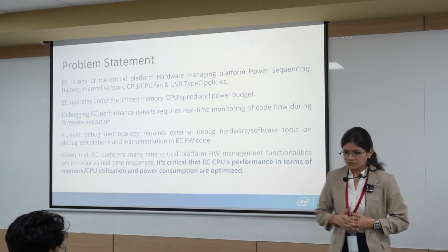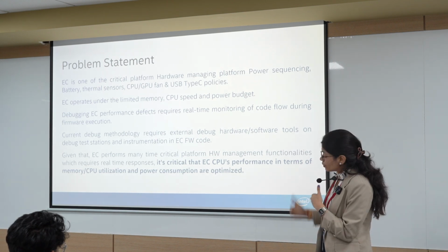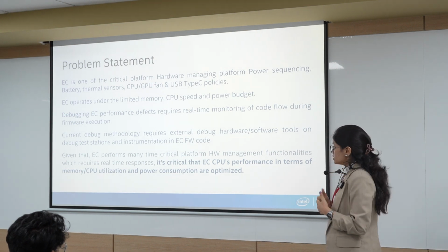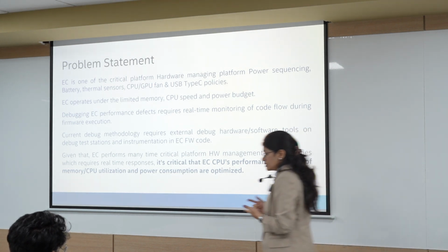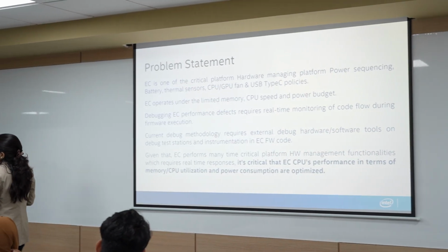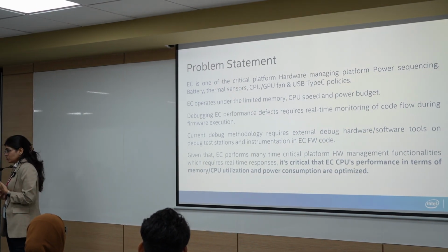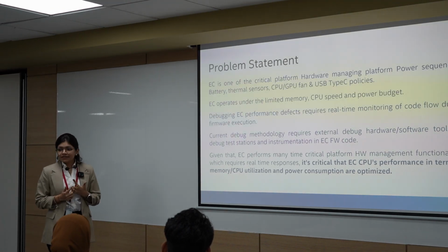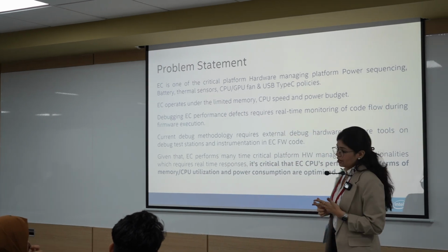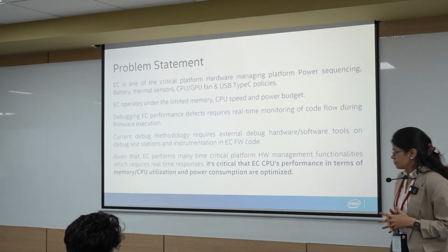Which module did it occur in? Using this tool, we are overcoming this kind of situation much earlier than the firmware release. This tool can give us RAM usage data, stack overflow, the worst-case stack scenario, and, another important thing, the data structure hole details also. So we can utilize the memory very efficiently. This is why we developed this tool using the Zephyr optimized tools themselves.